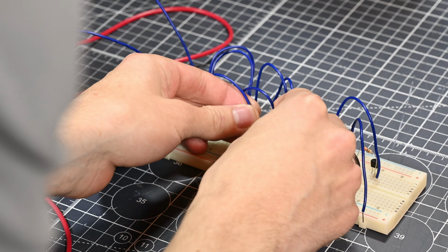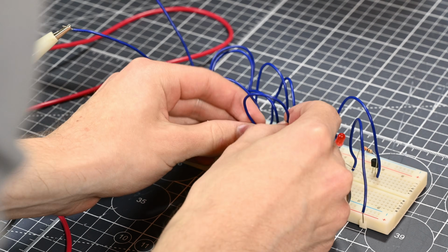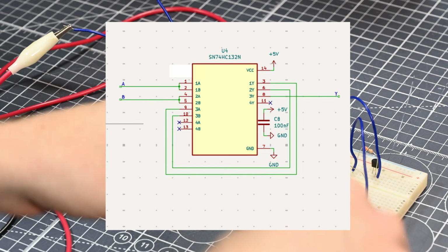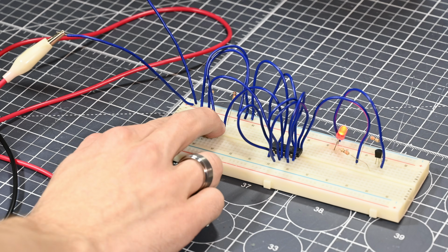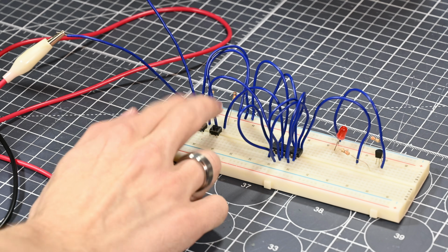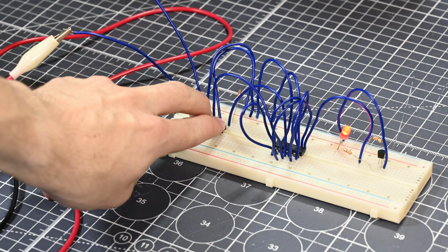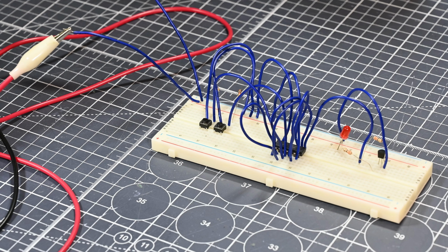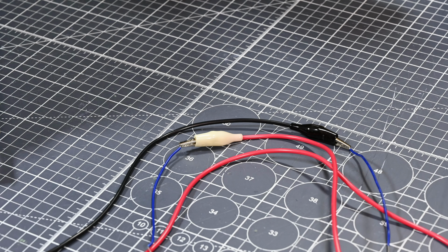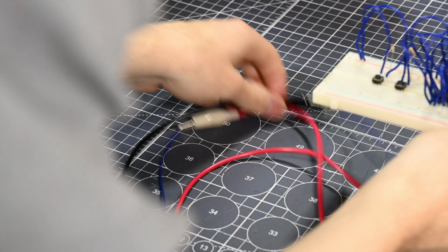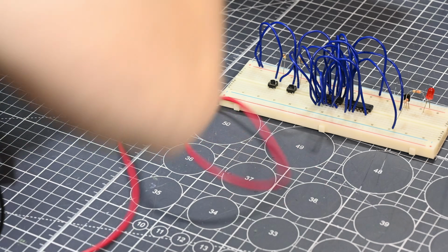How about we try reconfiguring these NAND gates again, and let's see what happens according to this schematic. Well, now we've created an OR gate, and this just keeps going for all of the other kinds of logic gates like AND, OR, NOR, and more. You can really see how the NAND gate is one of the most versatile types of logic gates through this behavior.